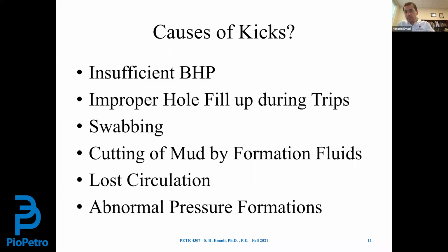If for any reason formation fluid starts entering the wellbore and contaminates the drilling mud and reduces the mud weight. If lost circulation happens, the level of the drilling mud inside the annulus drops, consequently bottom pressure drops, and a kick happens. Or if we are drilling and none of these happens, and we start entering abnormally pressured formations.